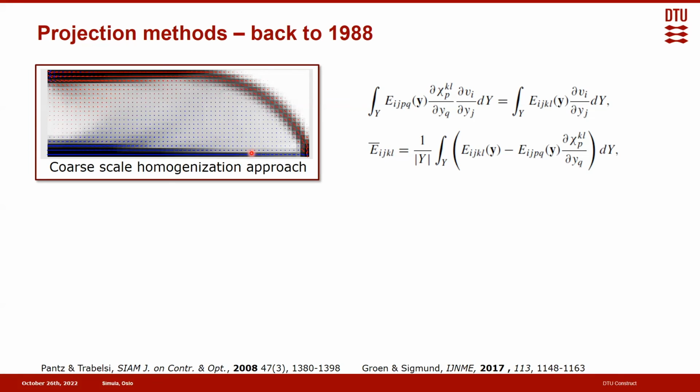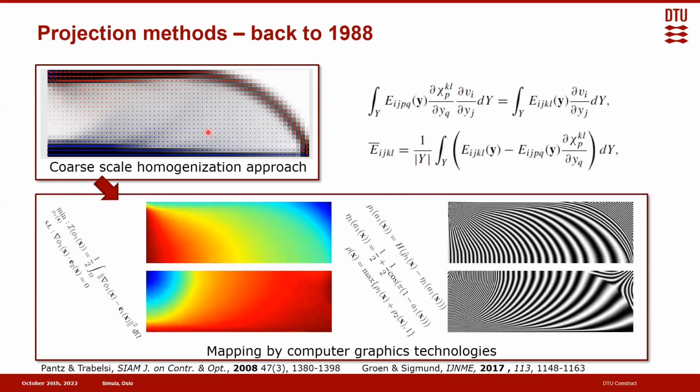So for a rank 2 material in 2D, consider a box with a hole, and then you orient that box. That's what you're doing. But of course, you cannot go and produce a design like you see here. But what you can do is interpret what you're seeing as a field. You can see this as 2 angle fields crossing each other. And if you extract the angles and solve a couple of auxiliary optimization problems, which are really nice, these are convex, solved like that, then you can get these nice zipper stripes out of it,